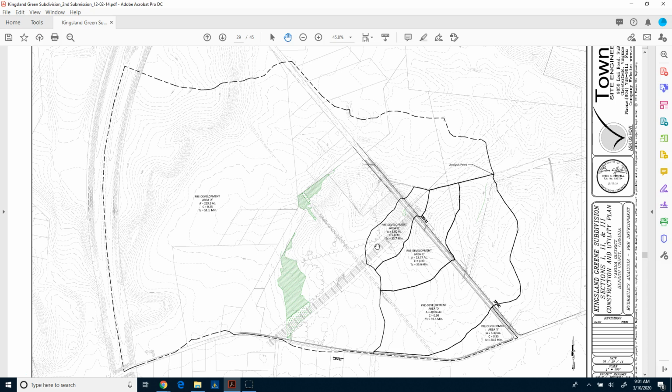So there's a certain formula and calculations to determine the runoff and the coefficient, and what type of soils come into play, what type of vegetation's on that site, and what type of impervious areas, or areas where the water is going to run off. That all has to be calculated in to determine what your hydraulics is. So what is it before you do construction?